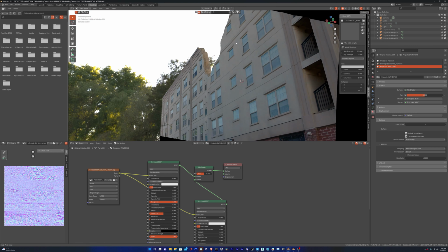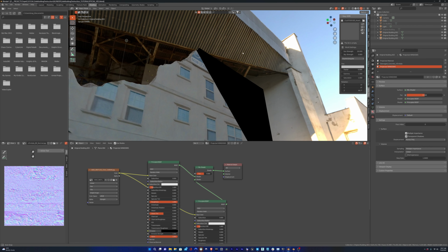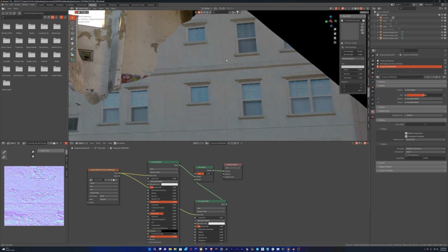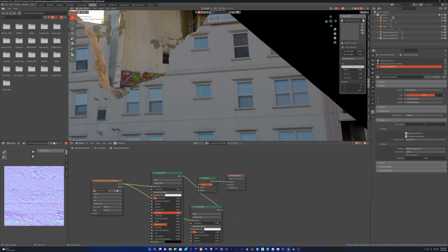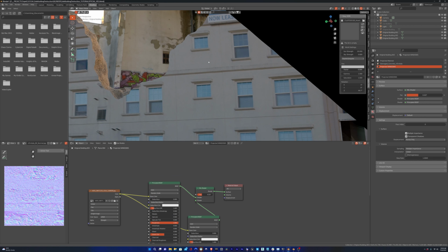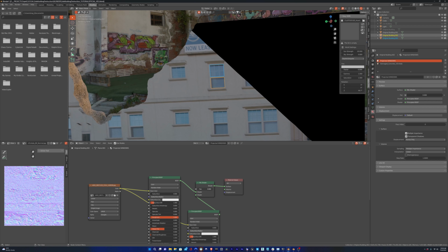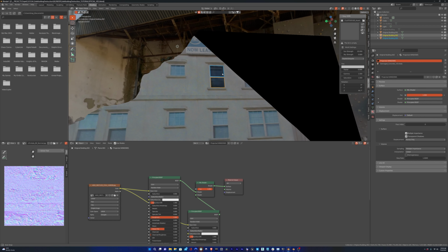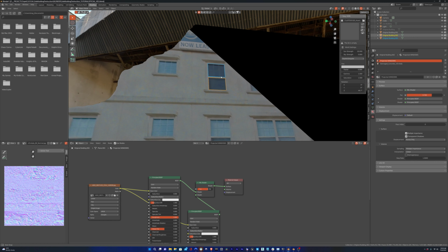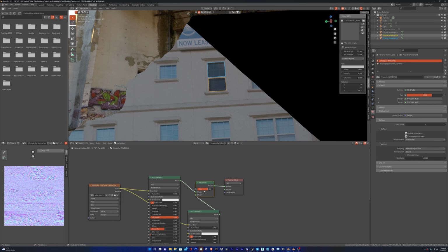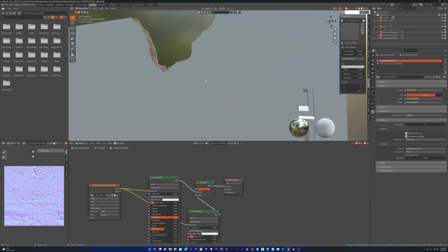So now it might be hard to see, but if we just exit out, if we rotate around it, you can see that there's a live reflection there. I'll take the transmission and I'll put it all the way up to 1. And then to mix this, you can mix it with the factor. So let's just kind of zoom in here. If we turn it all the way down, that's the original projected material. If we turn this up to 1, you can see that that's there, and we get that reflection. Now it's turned dark, so that's why I was saying maybe like 0.75 or 0.8 might work. So let's do 0.7. Let's try that. And as I move this around, you can see that there's a reflection there. So let's do 0.8. You're just going to have to go around and do that for all of the windows.